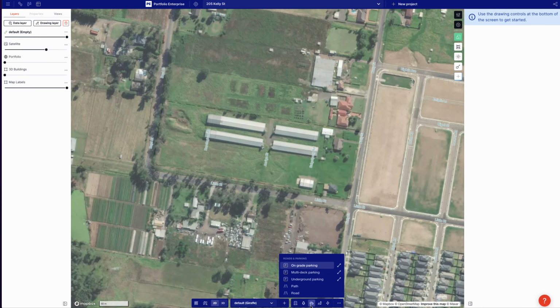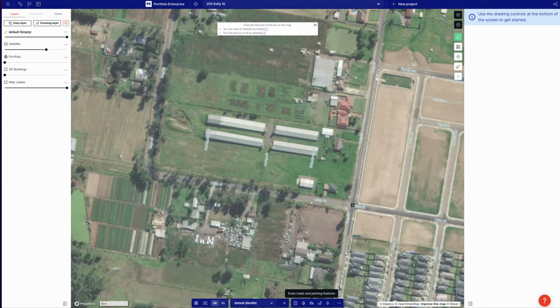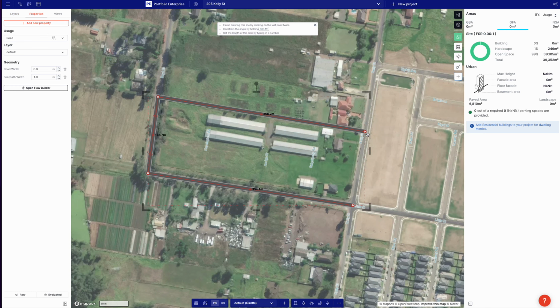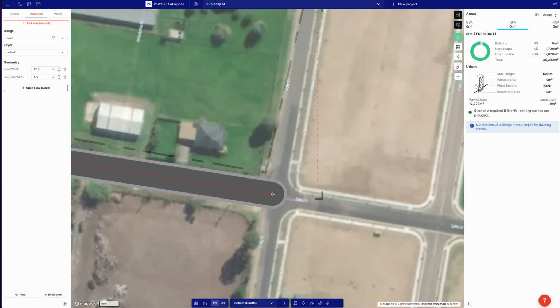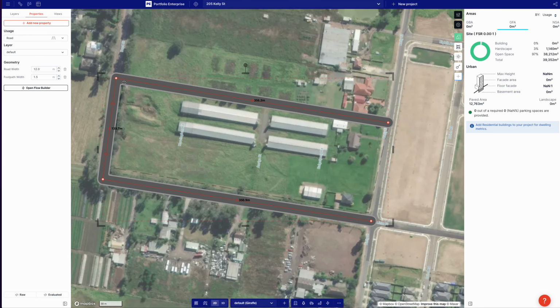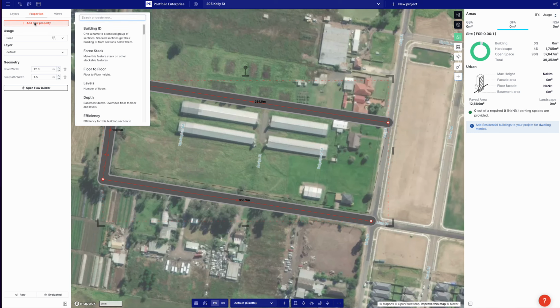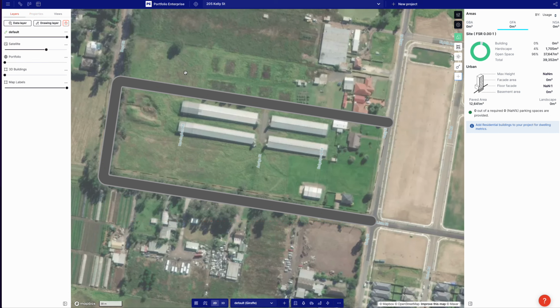All right, so armed with that knowledge, I'm going to do a very, very quick one. I'm going to model this street up, and then I'm going to assume that we're going to do something like this. Now for the street, I'm going to set that to a 16-meter street, which seems too big. So I'll go down to a 12-meter street, which seems more accurate. And I'll do a 1.5-meter footpath, which seems roughly right. Giraffe will solve those road intersections for me. What we can do is add a corner just to radius them out, maybe 5 meters.